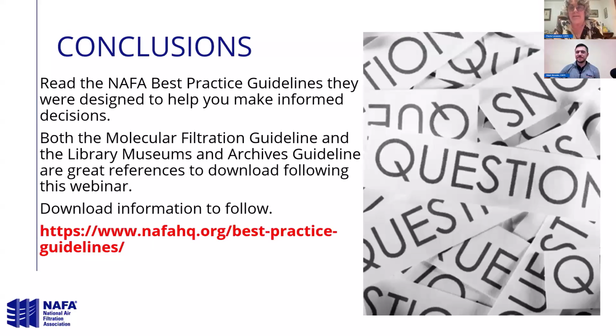Obviously, there are products that remove CO2. They are operated at zero humidity and a really exact temperature. One of the products is called Hopcalite, if you want to look at it. It is what they use in things like submarines, because obviously they have to get rid of CO2. You are not able to use it in a commercial market because you can't control the conditions. The conditions have to be perfectly controlled in order to do it. So if you want to get rid of CO2, bring in some fresh air.